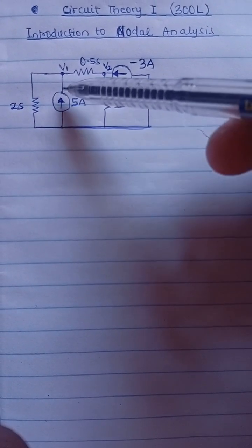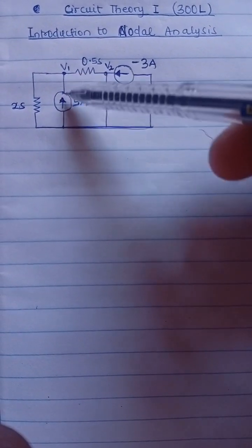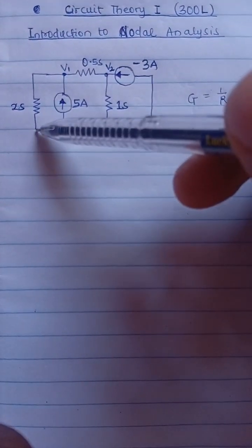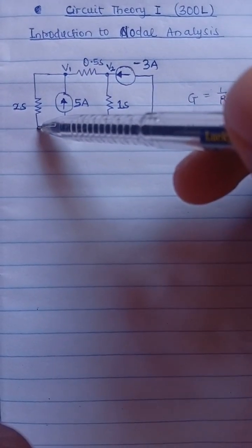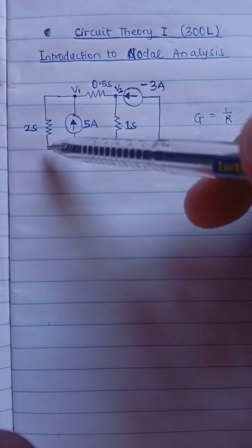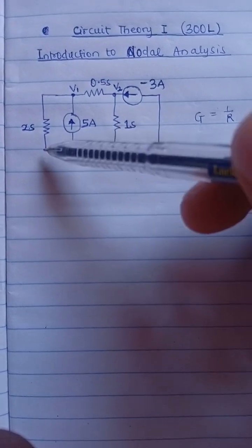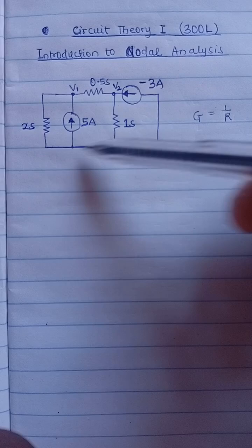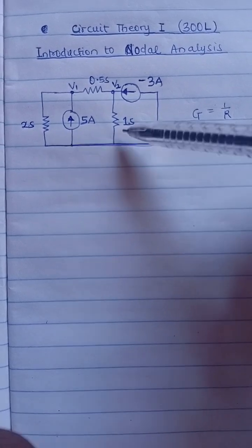Why is this a node? Because this circuit element, which is a current source, joins with a resistor and another resistor. This is the junction where they meet or join. So that makes this place a node. How about this point? One might ask, well, this is not clearly a node. It's actually a node, but a trivial one, in the sense that you can itemize this place to be the junction where a resistor joins with any other thing. This is just some piece of wire, if you can see.